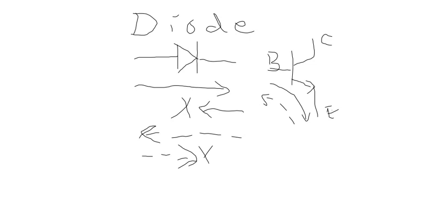But the left-hand rule says if I take a solenoid, which is a coil, and run a current through it, I wrap the four fingers of my left hand around the coil in the direction of current flow. Now they don't specify, but what they're using is electron flow. Use your left hand for electron flow. Use your right hand for conventional current flow.